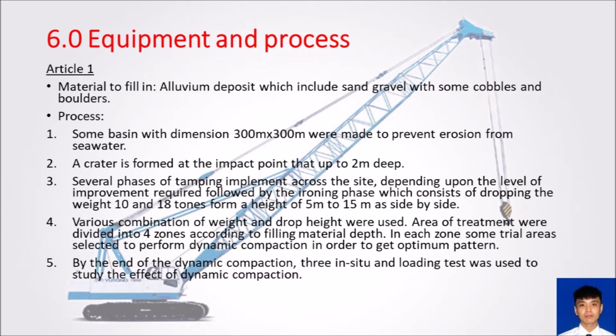Next, various combinations of weight and drop height were used. The area of treatment was divided into 4 zones according to filling material depth. In each zone, some trial areas were selected to perform dynamic compaction in order to get optimum patterns. Last, by the end of the dynamic compaction, 3 in situ and loading tests were used to study the effect